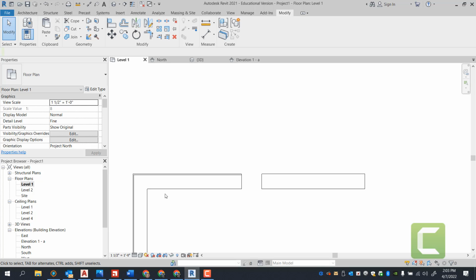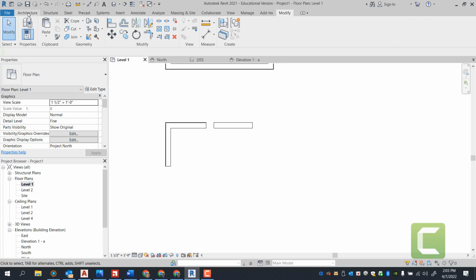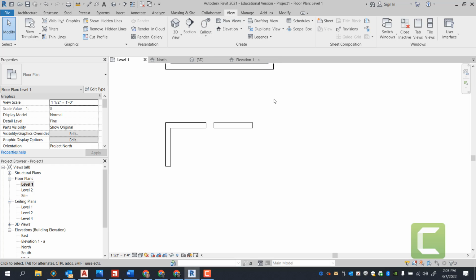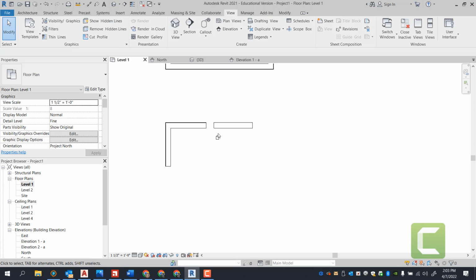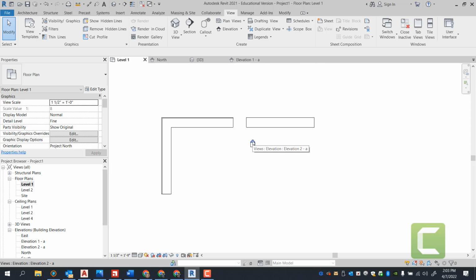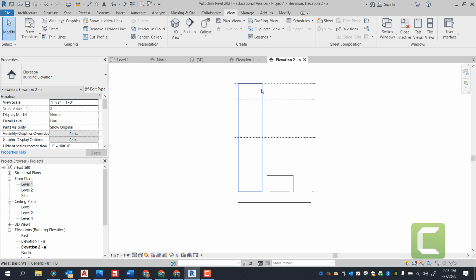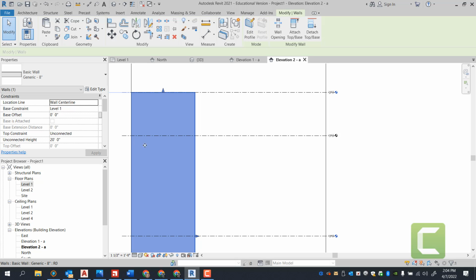Oh, like half wall, like elevation wise? Yeah, so if I was to put an elevation marker here, creating a new view, elevation, looking this way, click on the arrow. This is the extent of the view, this is the depth of the view. If I don't want to see the building in the background, pull it back, double click on the arrow. That's a half wall, that's a full wall. This went all the way up to unconnected height of level 4, which is 20.